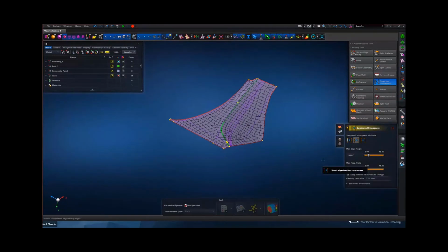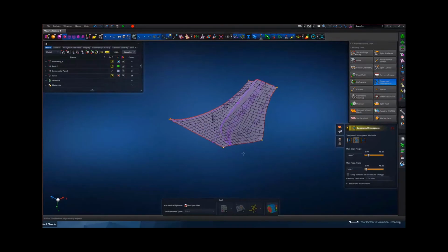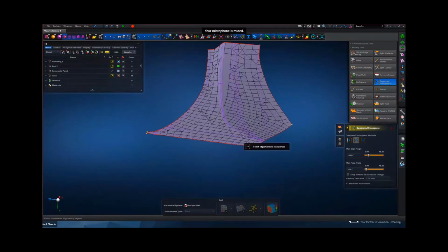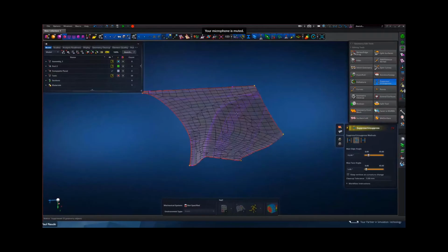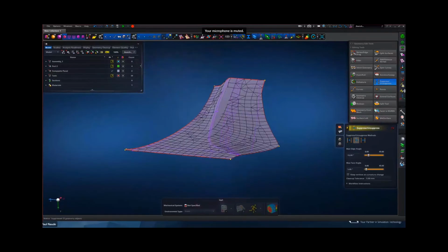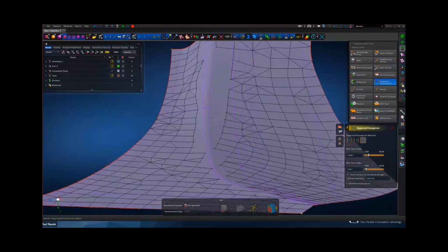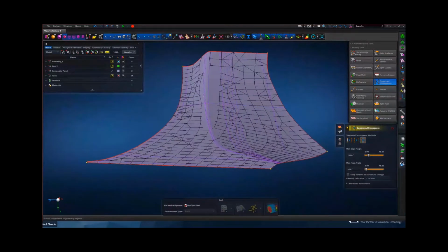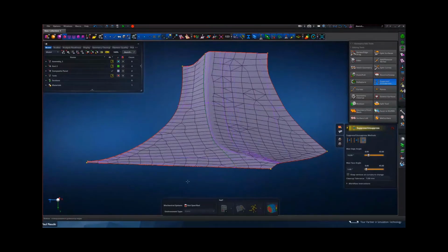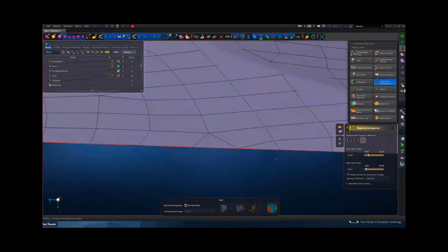Okay, but that has to do with a little tick box over here. And this I've only found out recently. If you untick that, it's actually much more aggressive in how it will suppress features. But now, as you can see, my mesh can literally take a shortcut, and that is probably not what you want. So you can reverse the process by simply, again, selecting contiguous edges. The shortcut is Alt double click.